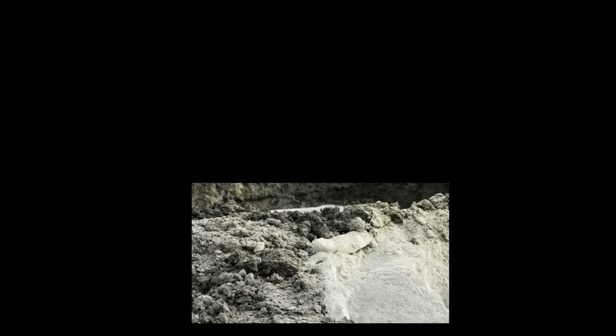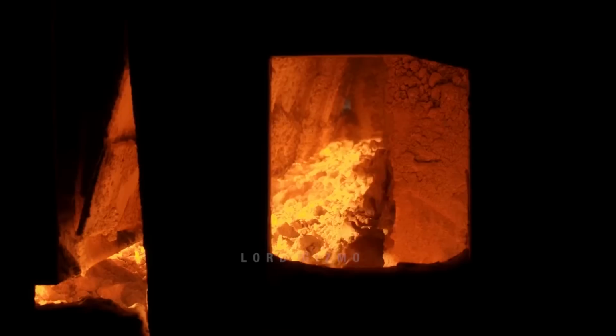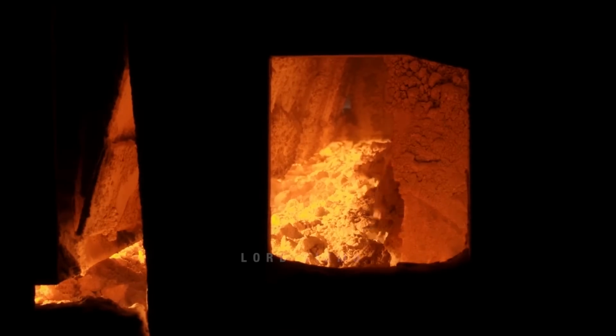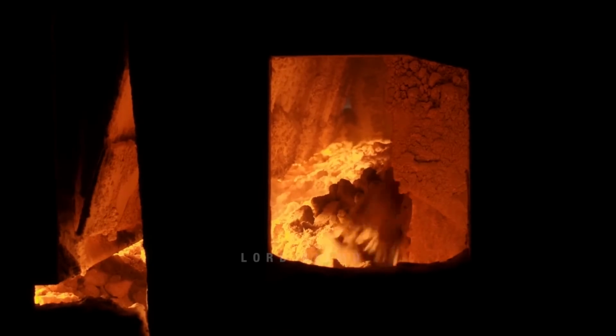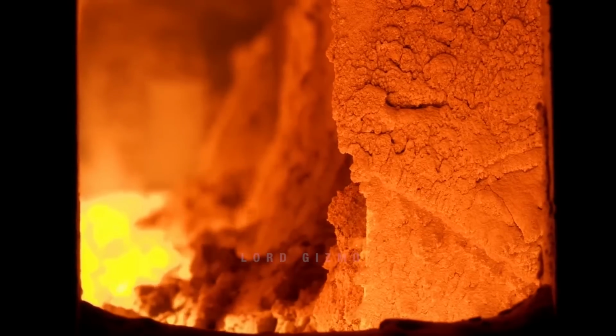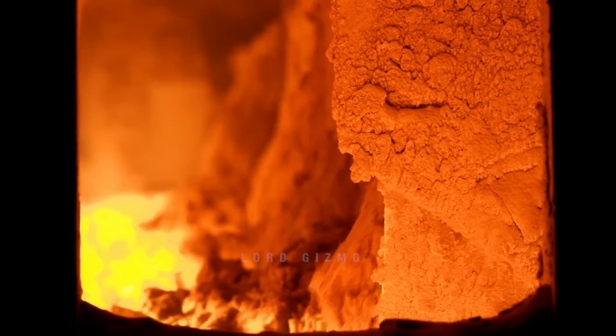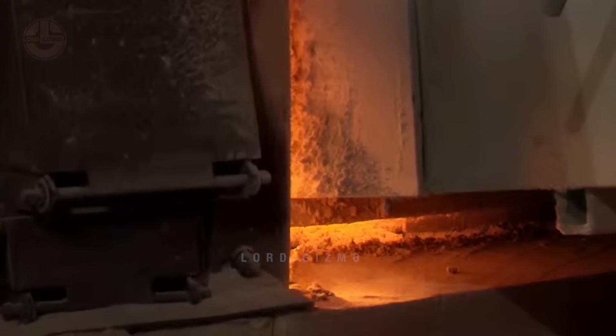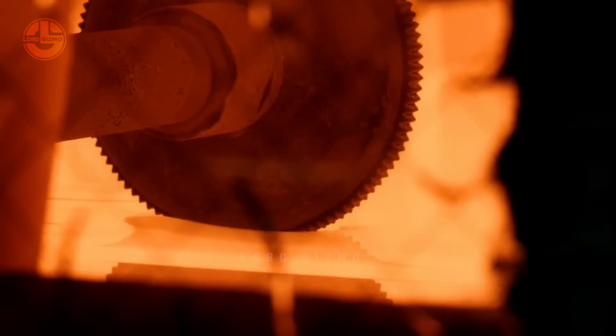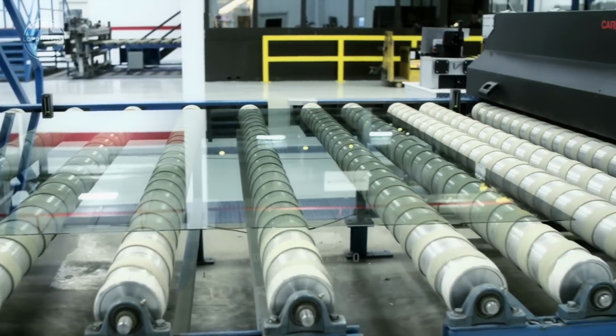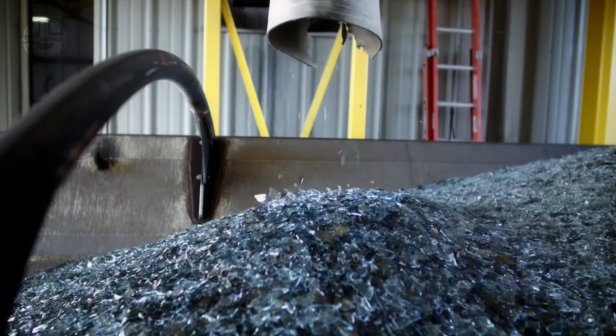They may include soda, lime, and aluminum. Soda lowers the melting point of glass compounds, lime enhances their stability, and aluminum makes them tougher. These ingredients are then mixed evenly in a specific proportion to make a specific type of glass. For manufacturing float glass, broken glass can also be used.